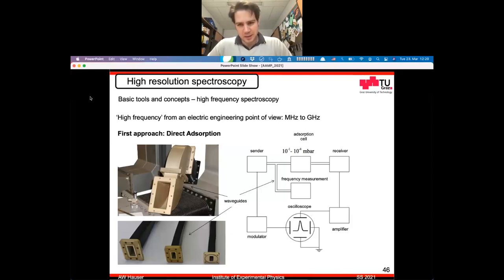And it's an interesting type of physics, because now our electromagnetic waves have wavelength in a macroscopic range, right? So they are actually something that you can really see in terms of extension in your lab, for example, by looking at those devices which are used to transfer power from a sender to a receiver. In this frequency regime, so from a gigahertz and up, it is more efficient to use so-called waveguides to transfer this power. And in German, you say Hohlleiter, so you can see one example here.